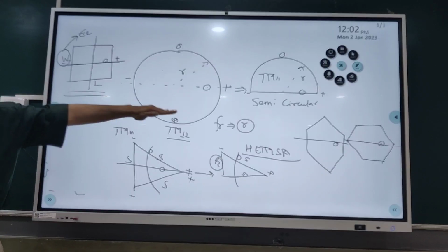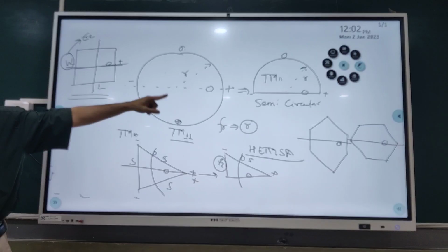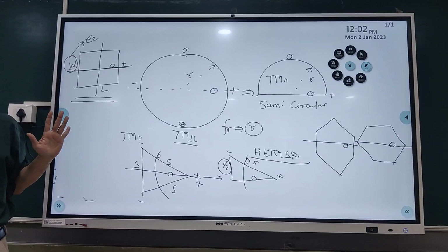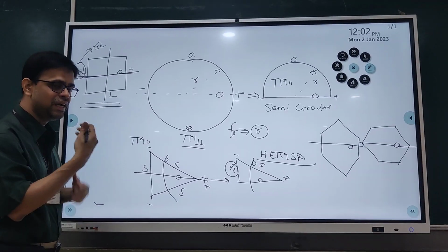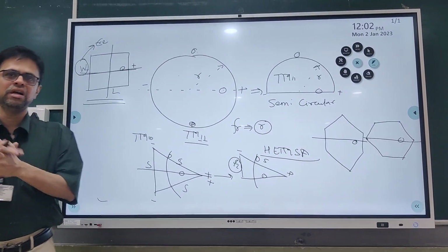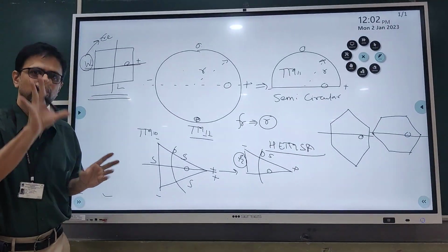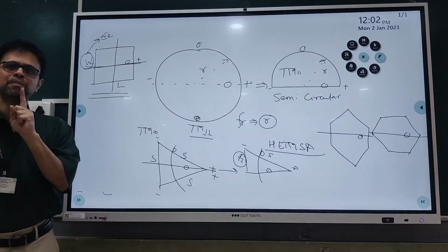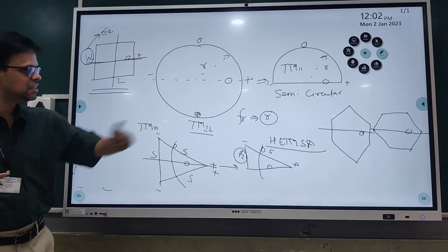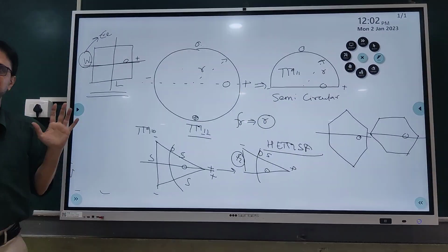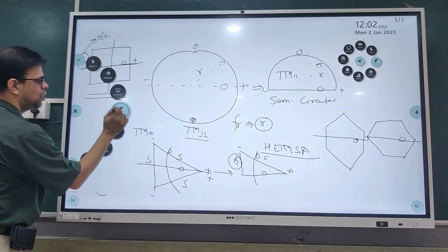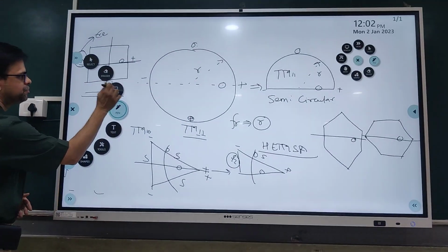Remember this, because the fields of the hexagonal microstrip antenna are similar in nature to the fields of your circular microstrip antenna. So depending upon the geometry, one can take a call by closely observing the geometry and then considering which parameter decides its resonance frequency. You can select a patch and realize a compact design using the symmetry of your configuration.